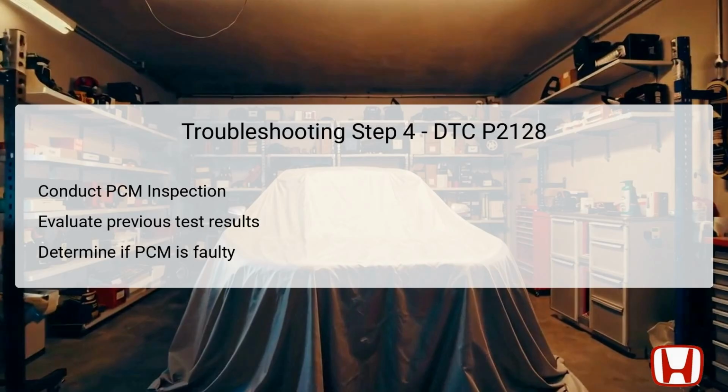The PCM is responsible for processing inputs from various sensors and controlling engine functions, making its reliability vital to vehicle operation. To confirm the PCM as the issue, technicians might use diagnostics to evaluate signal outputs and overall performance. If confirmed, the replacement or reprogramming of the PCM will likely be necessary to resolve the DTC P2128 effectively, returning the vehicle to optimal conditions.